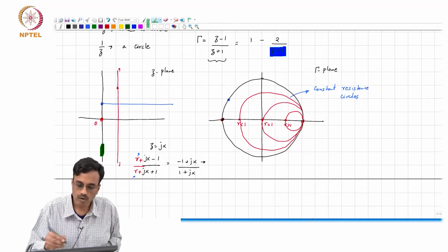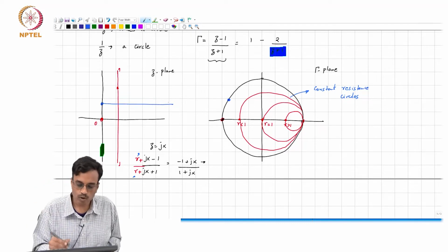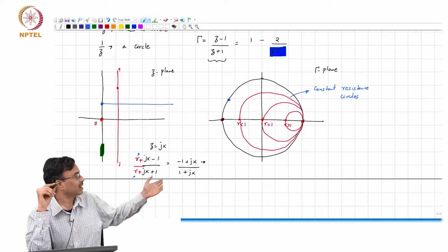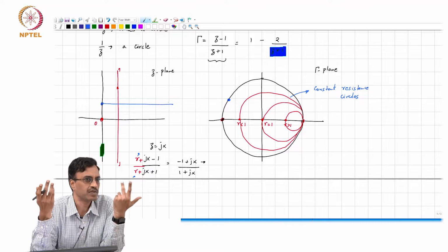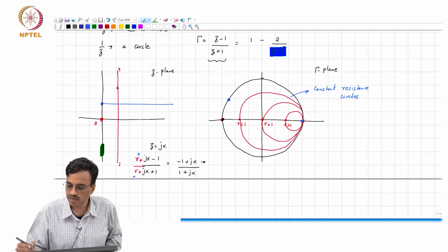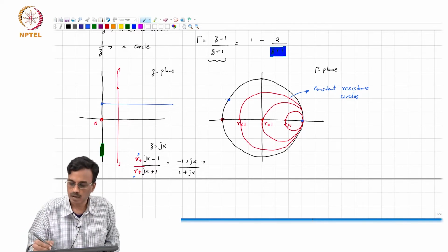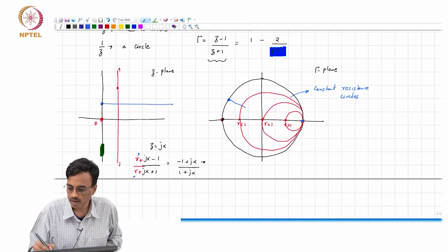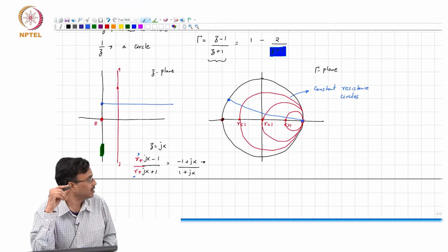Okay. So, we know what happens there, and as r goes to infinity, where are we? Whether x goes to infinity or r goes to infinity, it is basically like an open circuit where the reflection coefficient is +1. So, as r tends to infinity, you must go there, right? And how will it go there? It will go like a circle like this.